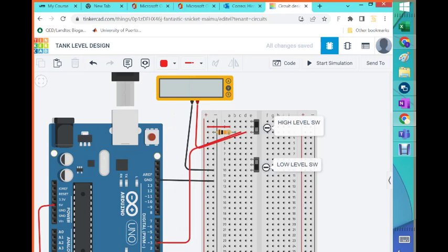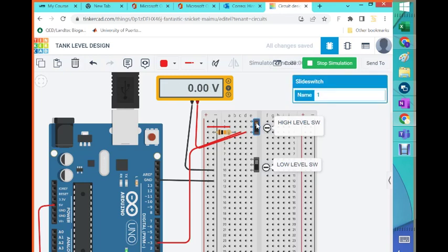So now pin 3, the instrument is reading 5 volt. It means that if I'm reading pin 3, there should be 5 volt as well here, arriving when this is connected. Right now it's in the connected state. I leave it there. I should start the simulation. I should see the 5 volt, but if I drop this to where it's supposed to be, it's going to be 0 volt. That's the way it is because it's normally open. So stop simulation, and we are okay.